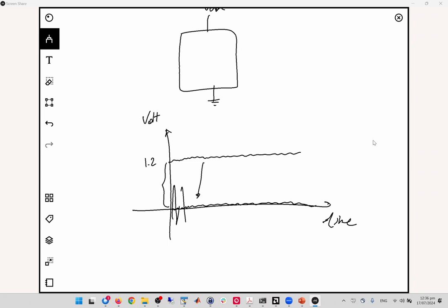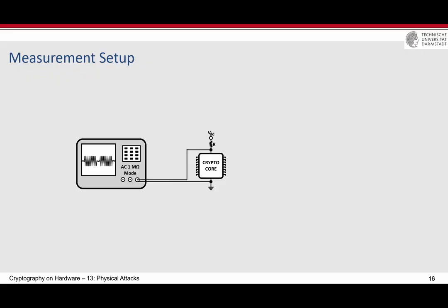When you increase the sensitivity of the oscilloscope, you can see the voltage peak to peak with much better accuracy. Because these oscilloscopes are digital oscilloscopes. They convert analog to digital, and this conversion is also not ideal. For example, they have an 8-bit or 12-bit A to D, where A to D is an analog to digital converter.